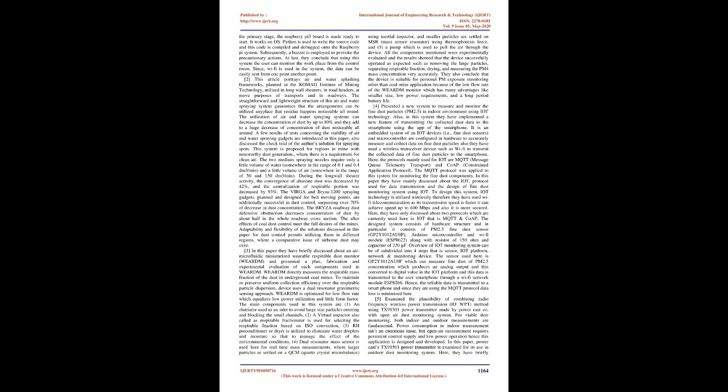the environmental conditions. 4. A dual resonator mass sensor is used here for real-time mass measurements, where larger particles are settled on a QCM, quartz crystal microbalance, using an inertial impactor, and smaller particles are settled on an MSR, mass sensor resonator, using thermophoresis force. And 5. A pump which is used to pull the air through the device.